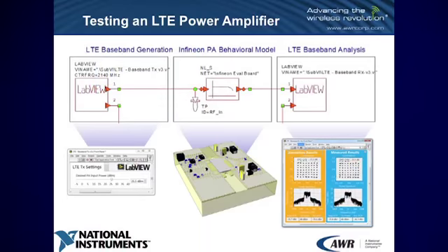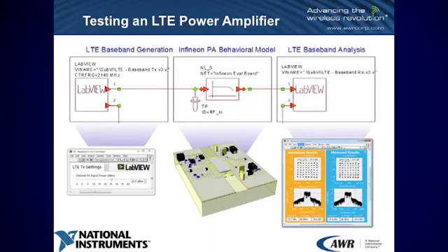One common example, and you can see the demonstration in our booth if you want to, is the simulation versus measured results of a complex device such as a power amplifier. Here you can see I'm using LabVIEW and the LTE toolkit in LabVIEW to create an I and Q waveform that I can send to another device. In a lot of other environments, this is encrypted, but in LabVIEW, this is fairly open, which means you can use a LabVIEW toolkit to create a waveform and use that with other generic signal generators, with MATLAB, or whatever else you want.